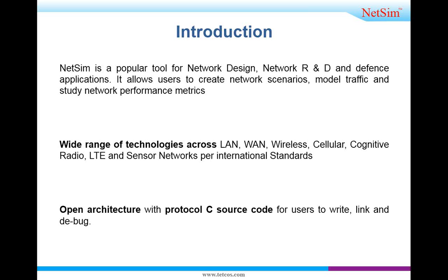Then it has an open architecture where users are provided with C source code of network protocols, which are implemented on all the IEEE and IETF standards. The purpose is to enable users to edit the standard protocol codes according to their own implementation, so that they can link it with NetSim and analyze the performance of the newly designed protocol.